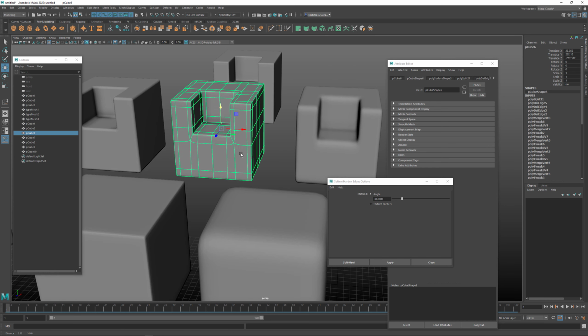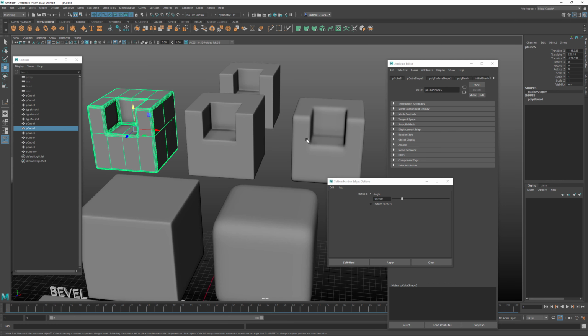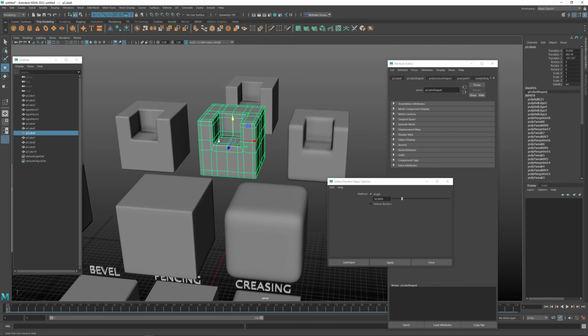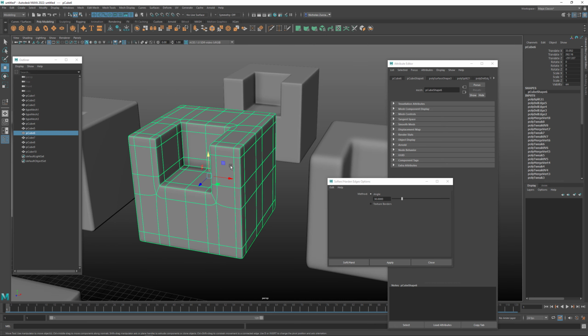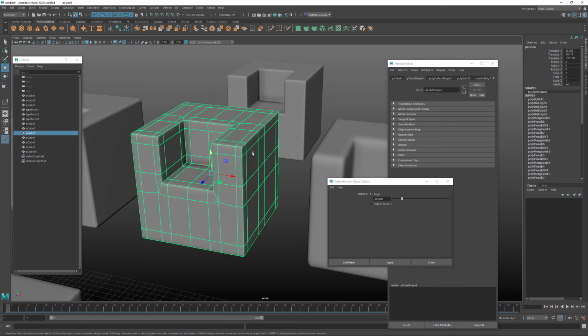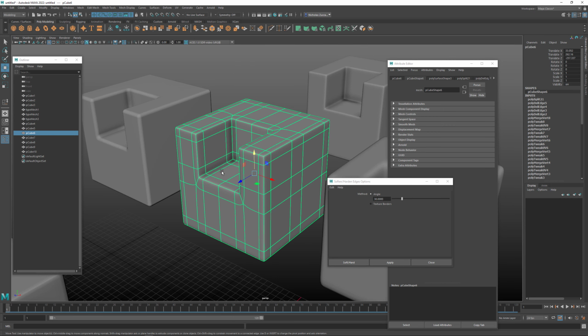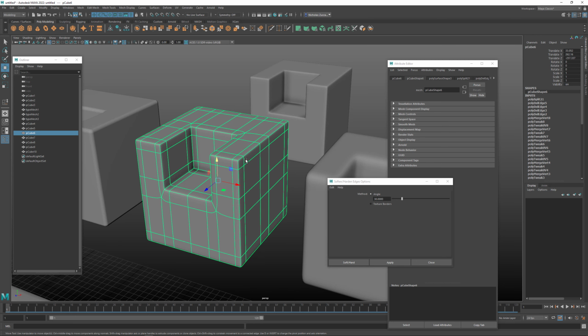And ultimately, even if you use some beveling or use some creasing, and then you finally end up getting to this method of using fencing, if you're going to model super, super clean, like I was saying, for something like the film world, your model at the very end has to have this fencing information, and if you tap 3, you have to do this smooth mesh preview, and you should have only 2 divisions on your model to get to what your final model is going to be whenever it renders, okay?